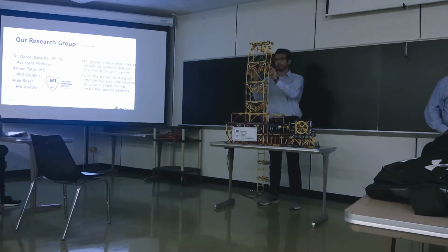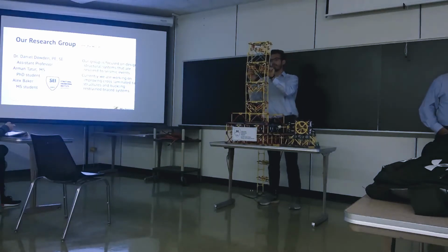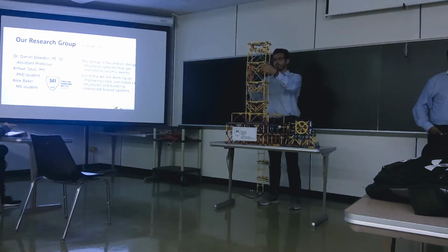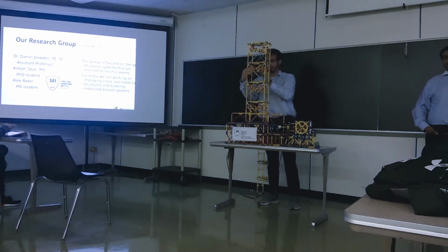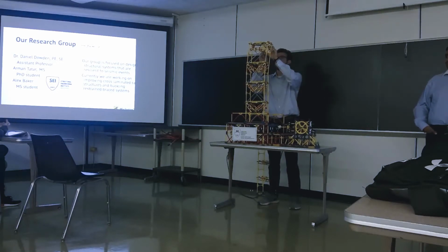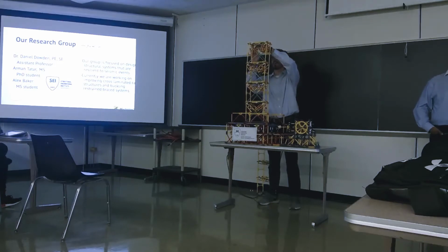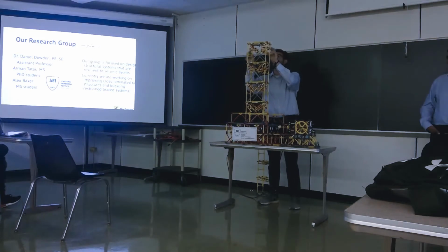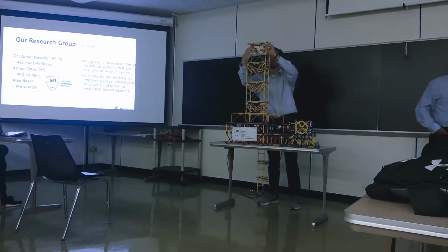Mm-hmm. Generally, it's always the fundamental mode which has maximum displacement. Yes, for the first frequency. So the top floor. So after looking at this, does anyone want to be on the topmost floor in a high-rise building? You know, the view is great, the wind is great, and everything is great, but you have vibration problems. You feel seasick all the time. Did you say it's the first natural frequency that makes the most displacement?